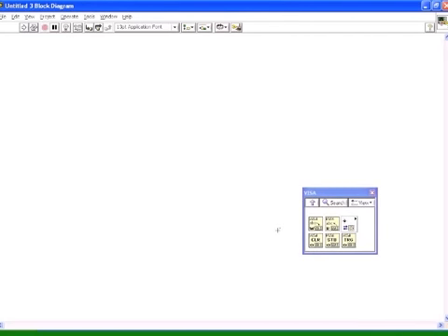And basically what we're going to be doing is sending SCPI commands, which means Standard Commands for Programmable Instrumentation, to a 33522A function generator from Agilent. I chose this particular instrument because it doesn't have a driver yet. There will be one, but right now if you want to speak to this instrument through LabVIEW, you have to use VISA and SCPI. Alright, now let's get started.